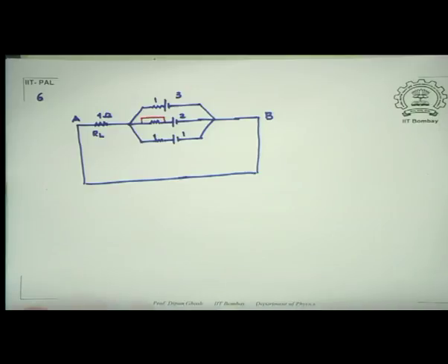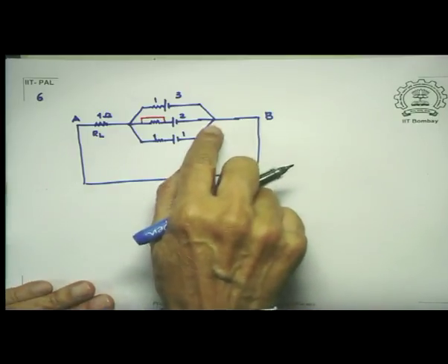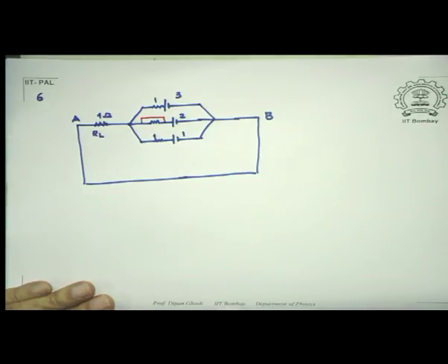So firstly, this is almost an introduction to what I will be later on discussing as the loop law, but I don't need it right now because that's the way I have been discussing. That is, I can go around any path as long as I remember the following. If I climb up a potential in a battery, I add that amount of potential. If I am traveling in the direction of current, there will be a potential drop of I times R if the current through the resistor is I. So let us look at what I can talk about.